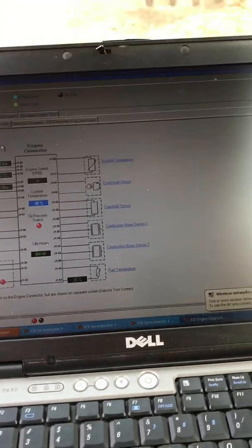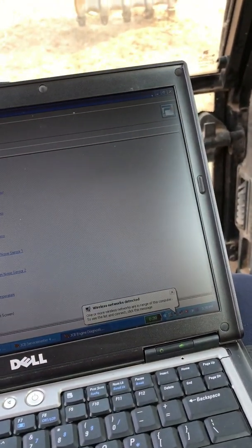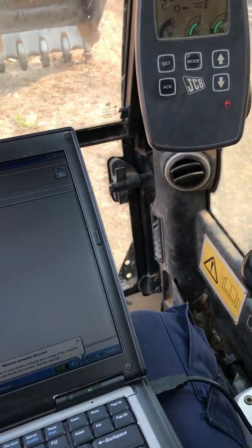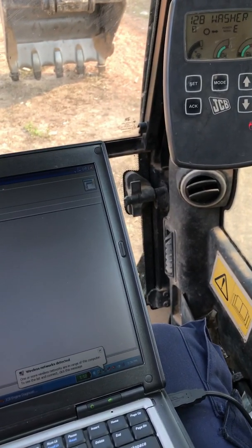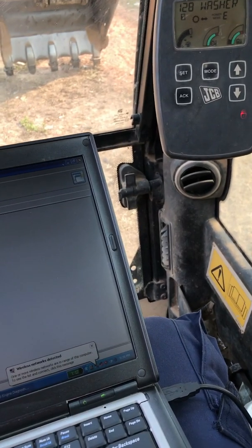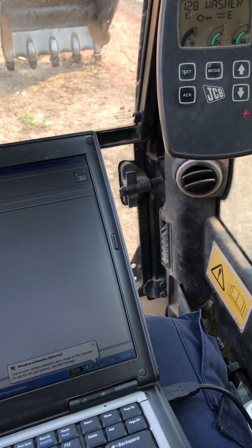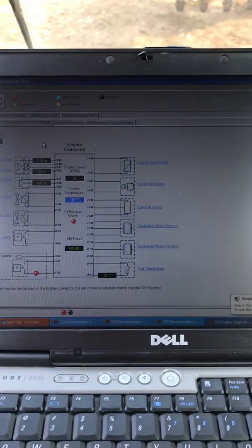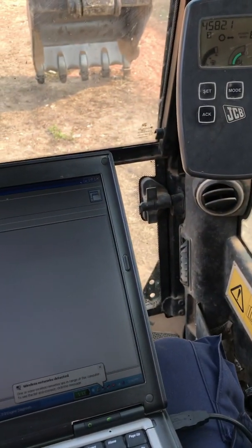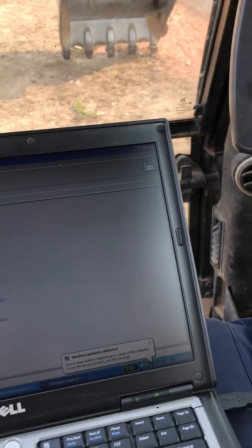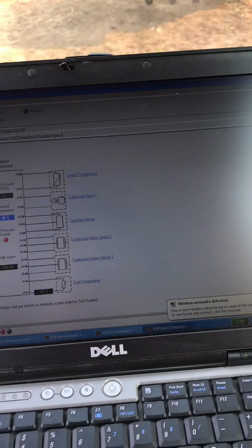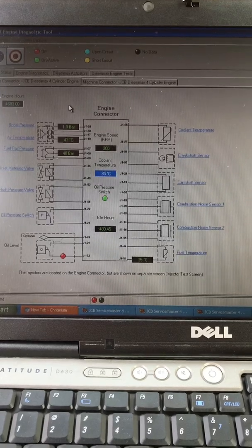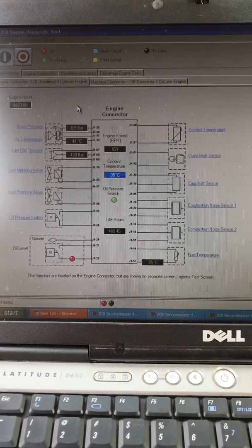Before we start, we have to make sure air is completely out of the fuel system. So we have to do that many times, key on, key off, for air bleeding out of the fuel system. But normally 5 or 6 times is enough. Okay, right now I did it about 5 times already. So this time I will start the engine. Okay, look at the status. So I will try. Your brake pressure is rising up, as you can see.